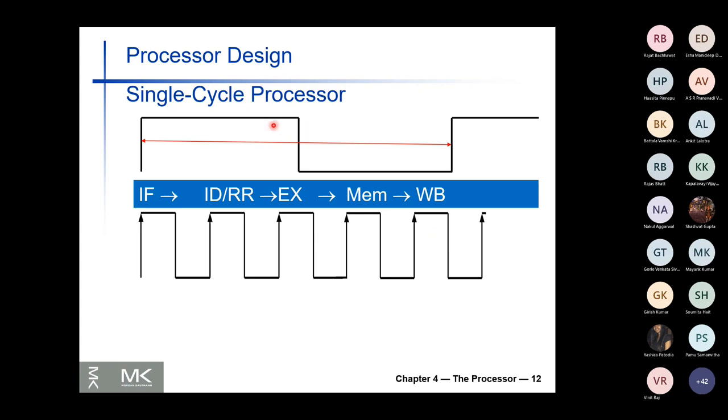So instead of having a single cycle processor, we have these basic steps like instruction fetch, decode, register, execute, memory, write back. So let us first make our clock faster. That means the clock cycle time becomes smaller. And what we do is that each stage of the instruction cycle can be finished in one clock cycle, something like this.